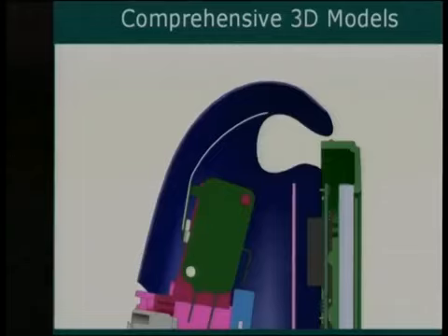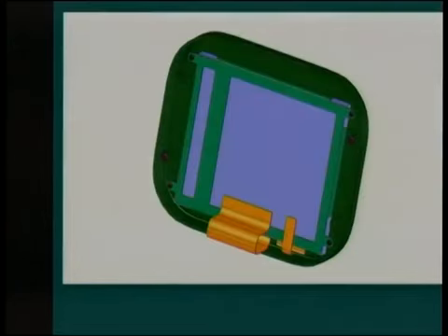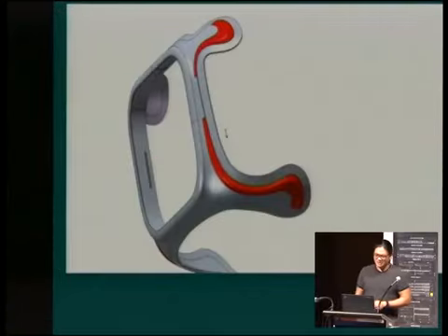Every design that you want to manufacture starts with a very detailed 3D model. We would model the circuit board and the parts on it, all the connectors, all of the holes, cross sections, the clearances, everything all done in a 3D model environment. It's very important to make sure your connectors don't collide before you actually make your product. It's unfortunate when it does, so we would take time to make sure that's okay. Make sure the LCD doesn't fall out, make sure the speaker boxes sound good and they're the right size and so forth. So we did a lot of modeling and CAD work.